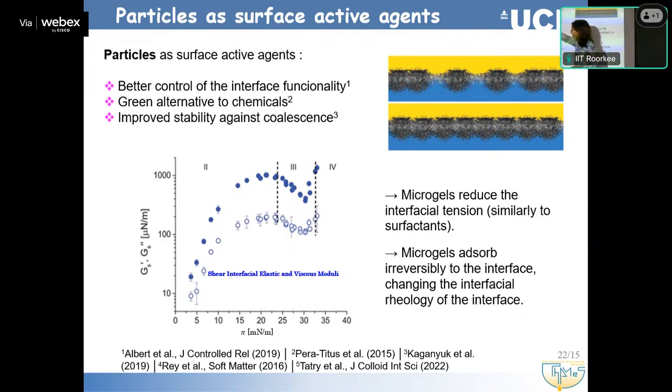And once we put the particles at the interface, now this is the behavior, the rheology of the interface. And you can see that the interface is elastic. So by putting the particles there, you are actually giving different properties to the interface, and it complicates the phenomena a lot more, because now, if we try to stretch the drop to detach it, your interface is elastic.